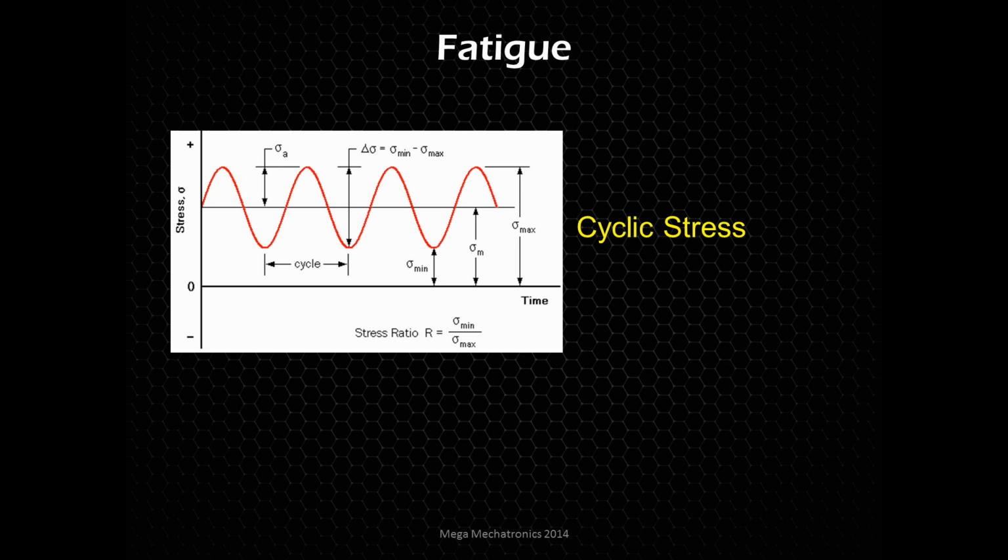In this particular example, very nice, even stress, and you see it's being stressed on the tension side. The space between the zero and the minimum of those valleys is a pre-tension, because it's not reaching zero, or it's not going into compression. So here it's just being stressed more, and then stressed a little less on the tension side.